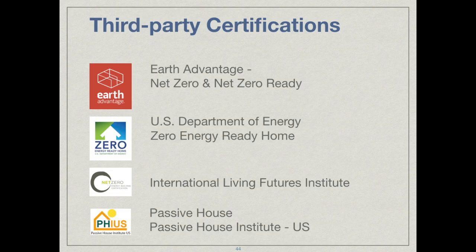And one of the things that I recommend people do is to choose a third-party certification program. The certification itself, I think, is valuable in terms of the resale value of the house. But the other thing that certification does for you is it gives you access to experts that are familiar with all these technical details, with products that are involved, and most of them require that you do some kind of an energy model. So your energy modeling step is kind of taken care of by doing the third-party certification. They'll also have someone come out and visit the house, inspect the insulation, the air sealing, the equipment to make sure that you're getting the elements that you're paying for.